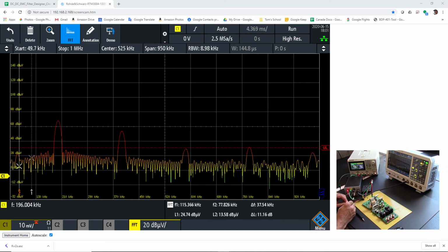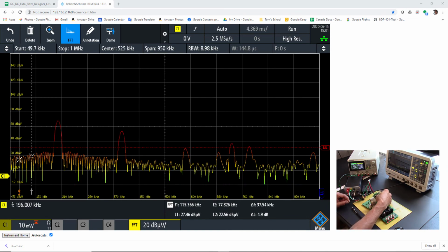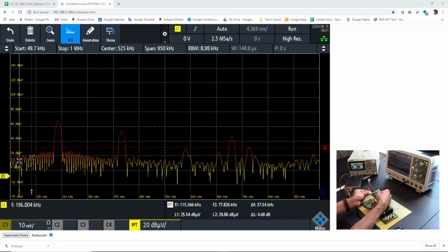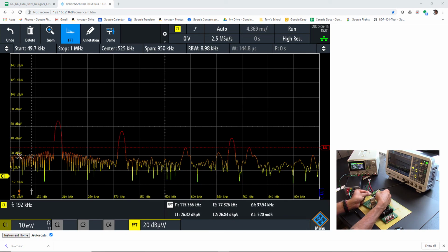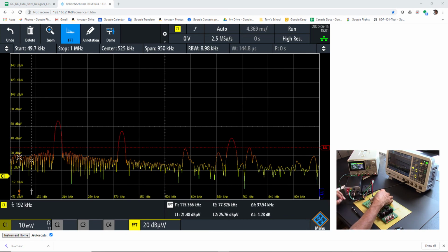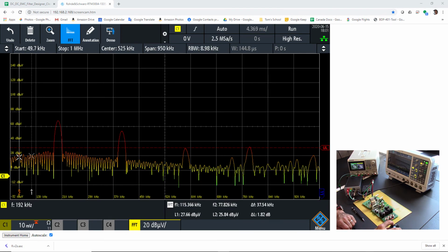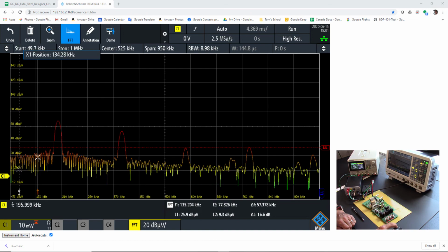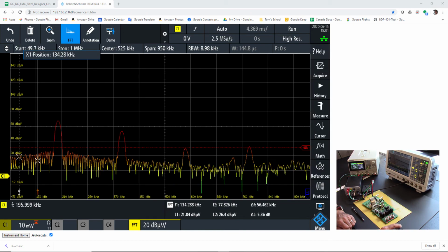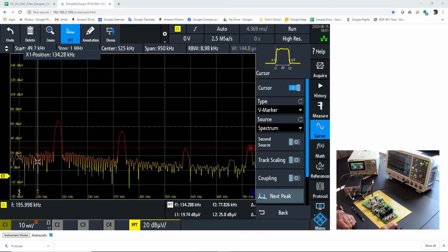but I don't have a pi cap at the moment. What we do in the class is that we add a pi cap manually. In a real converter or filter, this will be soldered on the board, but you'll see the impact in a minute. So first, let me look at the peaks after filtering. So I go to my cursor, next peak.